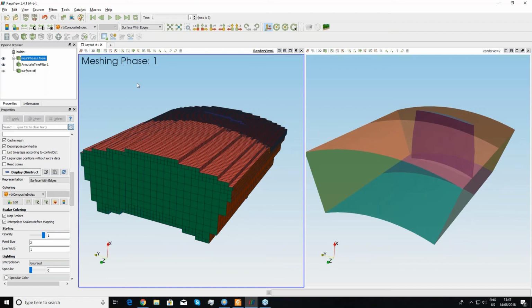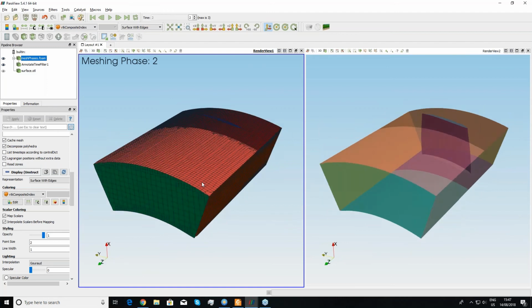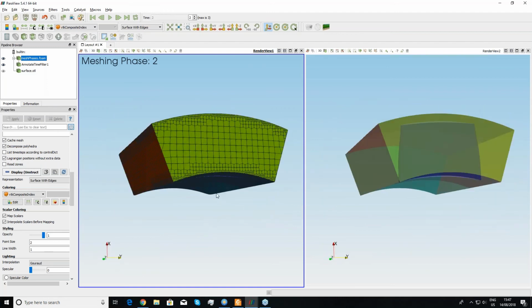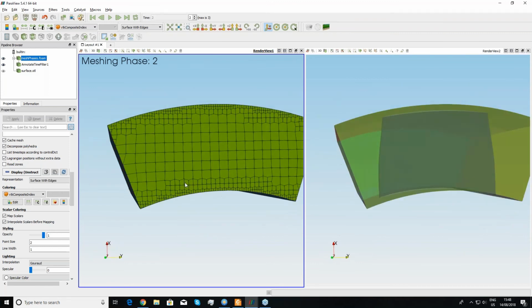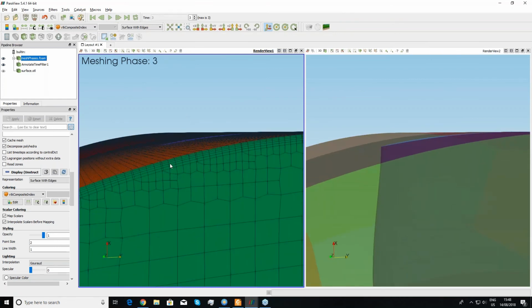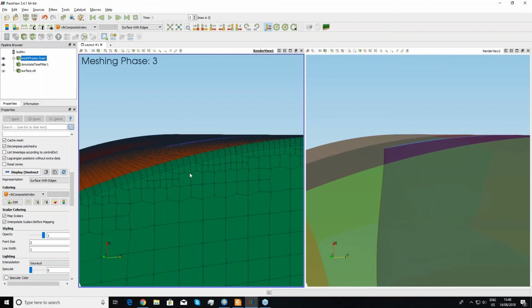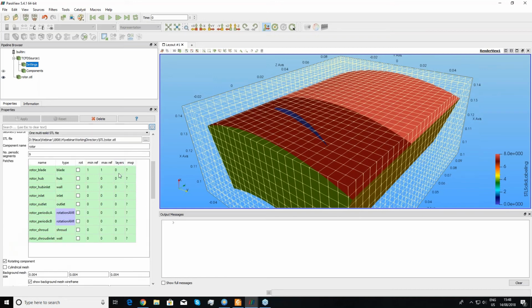Then the first phase, let's say. The second phase is that it is snapped to the geometry, therefore the name SnappyHexMesh. And the last part, if you define the boundary layers, is the third phase, where the boundary layer is generated. So these three steps are made, and now I think these parameters are more clear. So these are the refinement levels, and here the layers.